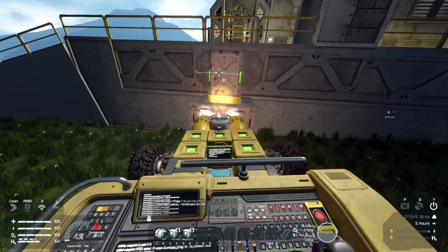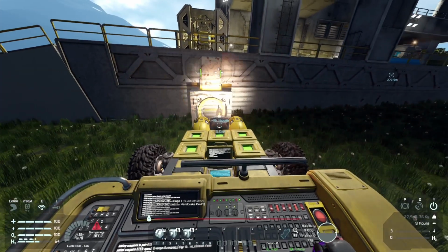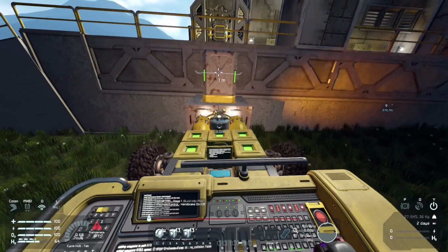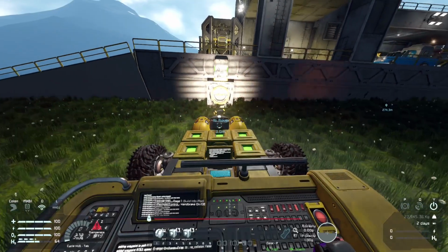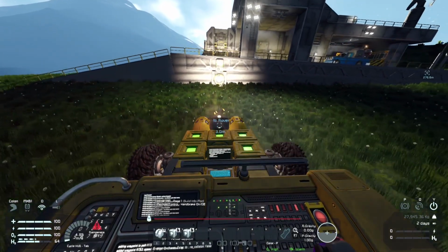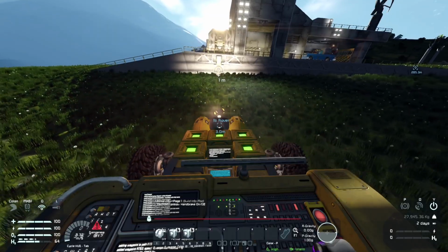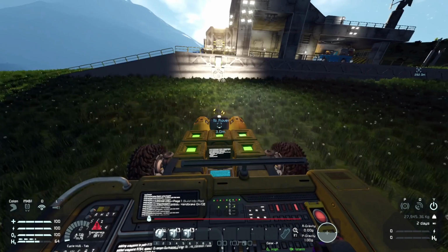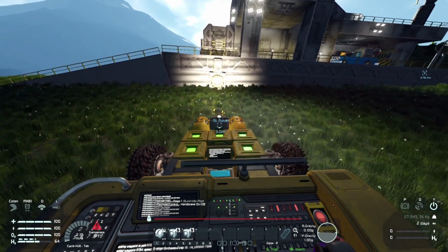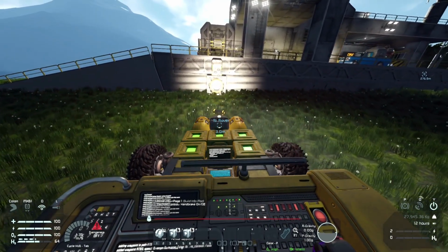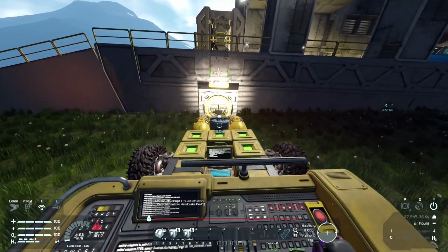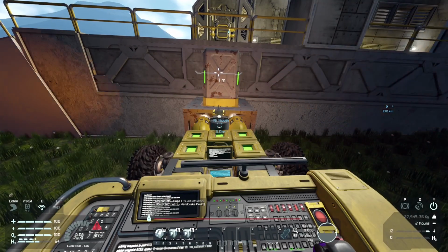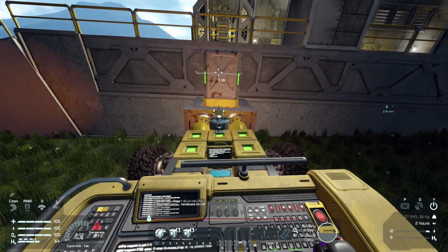And go ahead and take your time getting lined up. It is worth it to take your time and do it right the first time. So again, we're going to back up 50 meters or so, add our first approach waypoint, then about halfway between, add our second approach waypoint, and then this time we'll just press up against that and add our third.